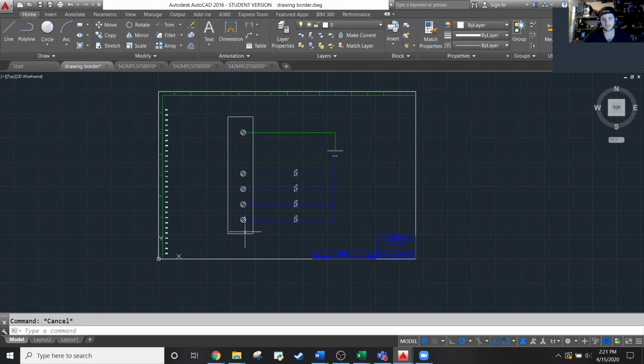Just be thinking about, if I'm making a huge set of drawings and I want to be systematic about how I'm assigning layers, what makes sense to you, and then just be consistent. And if you're running a CAD department, write it down so that everybody else knows why they have to follow that. Because if you don't have your standards written down, it gets really frustrating trying to keep everybody following them.